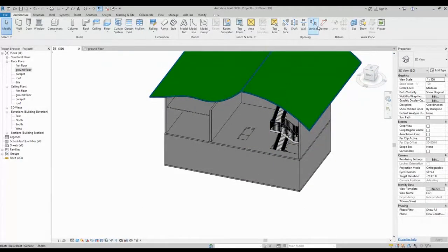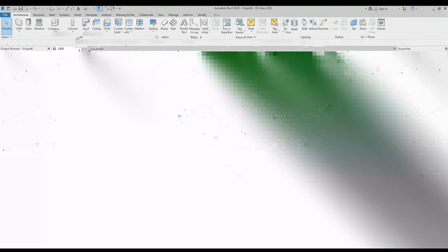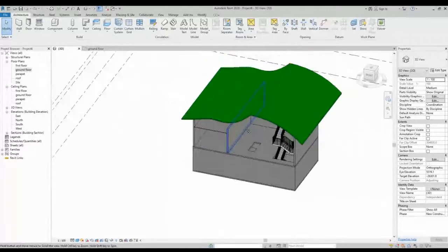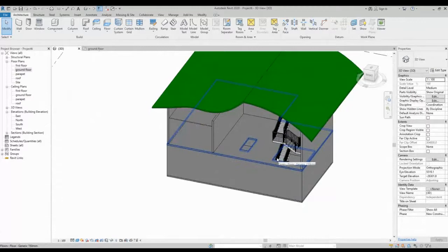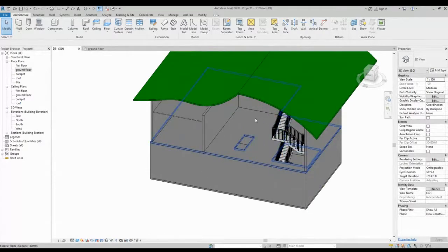Okay, so this is regarding the openings that we have. These are just refreshers on things that we've talked about before, but in a little more detail. Now, if I go to families, we've said that all the doors and windows that we're adding are families. You can add more families by going to component and then place a component. When you select place a component, you can select the category that you want.